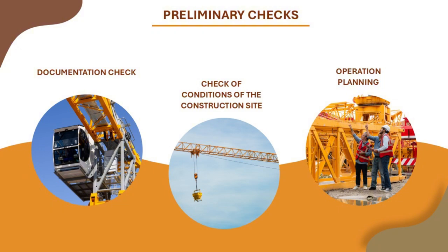Operation planning. Prepare an operational plan that defines the lifting and handling methods, the maximum loads allowed, the access and escape routes. Delimit the crane's operating area with barriers and signs to prevent unauthorized access.